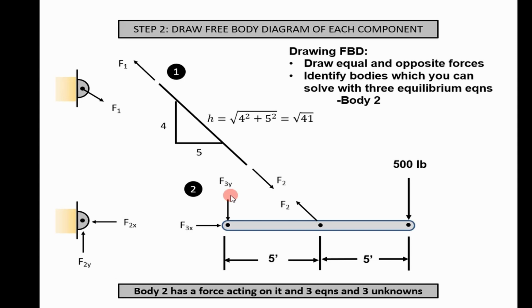Step 2, draw the free body diagram. I can't stress it enough. You got to break it down into a free body diagram of each component. And then you replace the forces where they touched with equal and opposite forces.